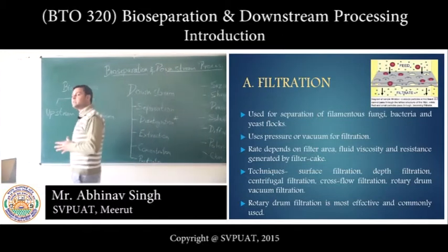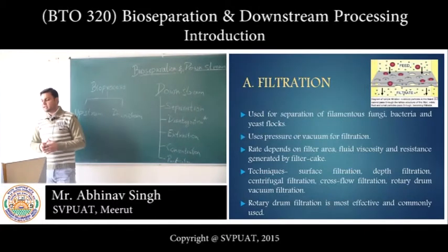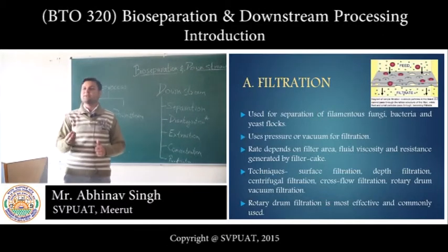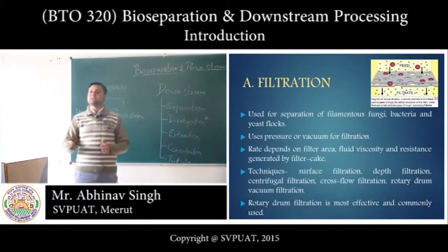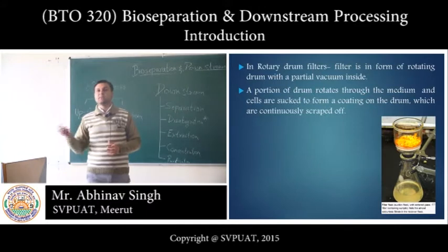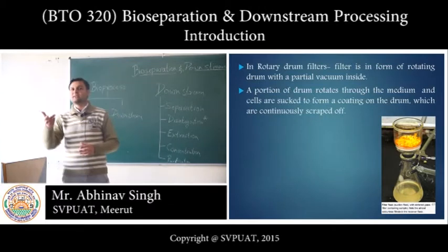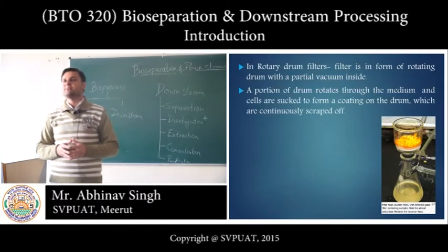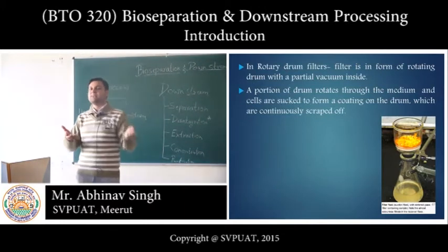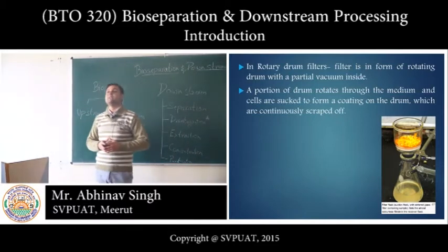There are many problems associated with filtration, for which we sometimes do not use this technique. For example, we have to apply pressure, either overpressure from above or from below. How are we going to create pressure below the system? We can create a vacuum inside the chamber wherein the filtration is being done. Another problem is if our product is very viscous. Imagine filtering something as viscous as honey: if we have a simple mesh and pour honey over it, will it be easy to filter? I don't think so. It would be very, very difficult.